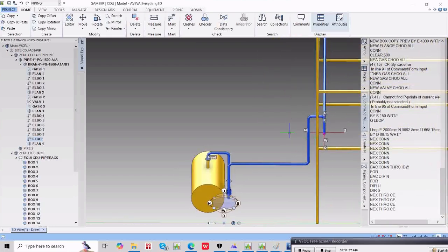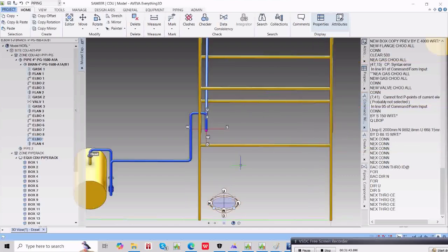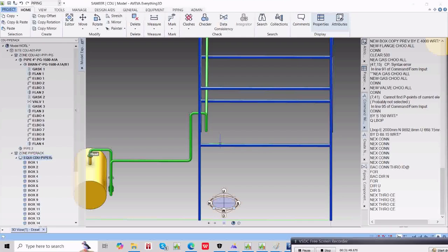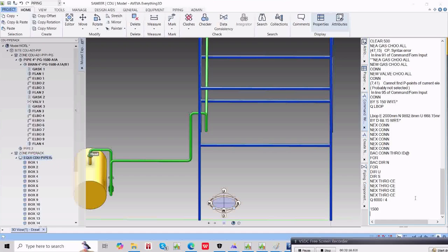As I already told you, there is a calculation and a placement arrangement of the line, and then the future space you need to consider in the pipe rack. Future space is based on the total width of the pipe rack. 25% of that total width has to be considered as future space. Right now I consider a 6 meter width of the pipe rack. So 25% of that 6 meters, for example 6000 divided by 4, so 1500 mm. A 1500 mm box has to be maintained here.